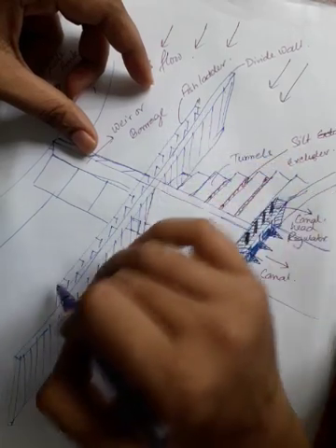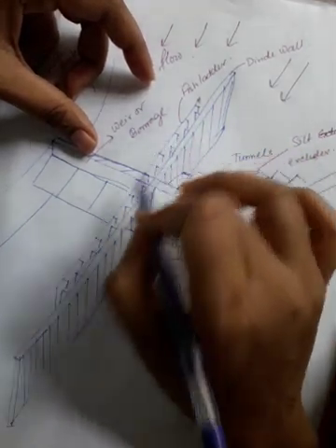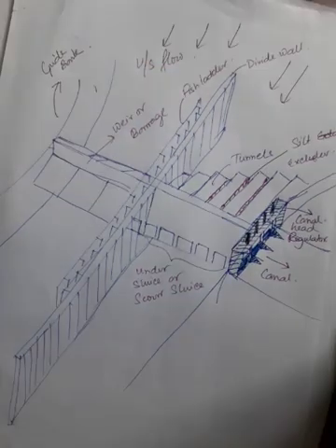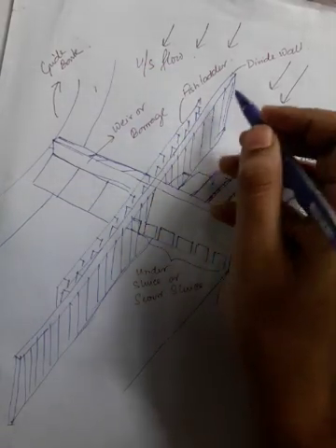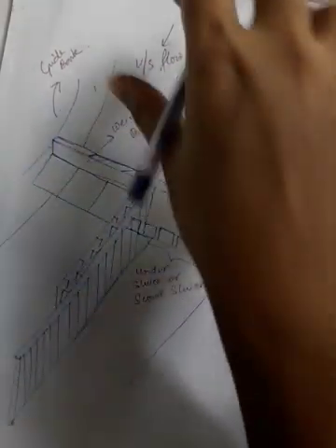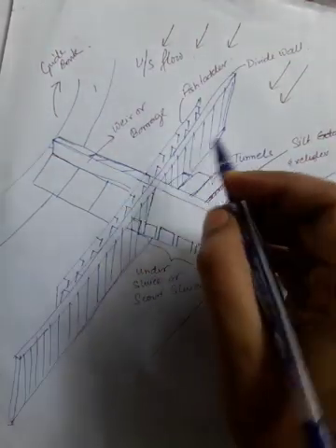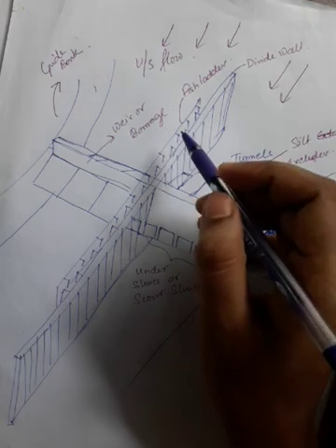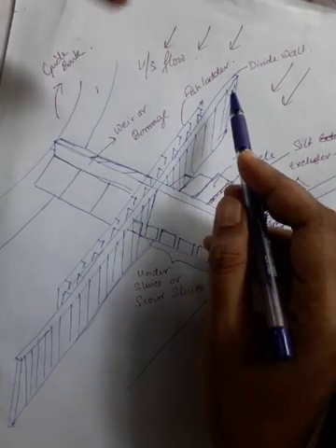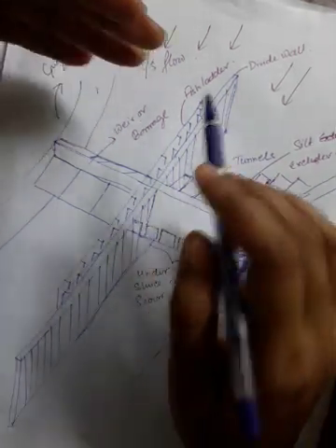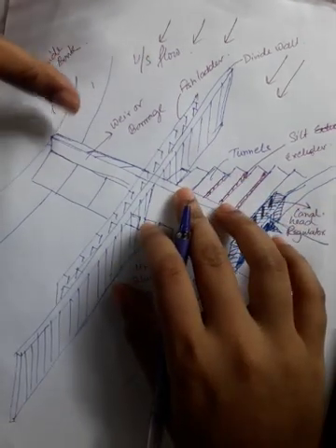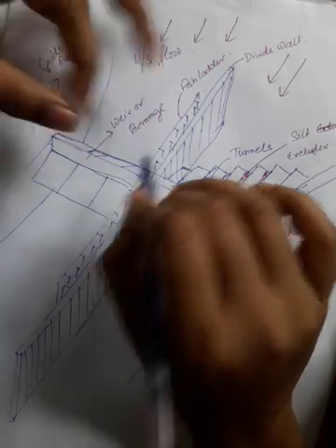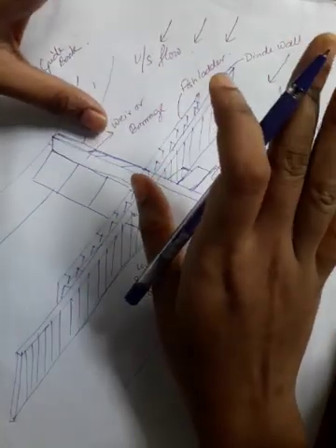This movement is very essential for their survival. It is quite hectic for them if we provide a barrier in front of the river flow. So this fish ladder enables the movement of the fish along the course of the river. Basically, the velocity of the flow within the ladder does not exceed 3 meters per second.